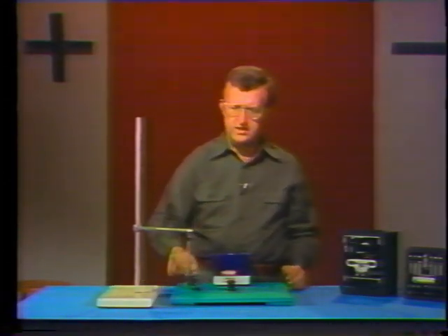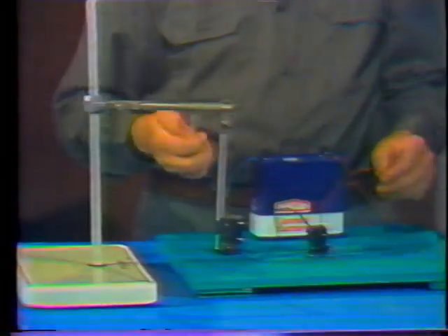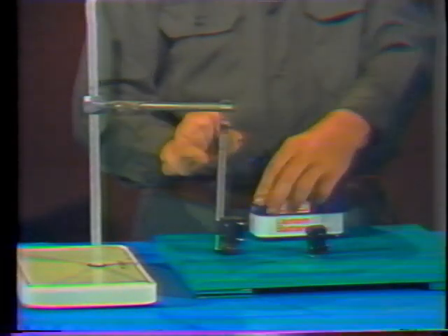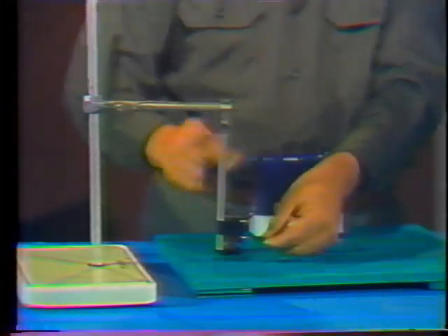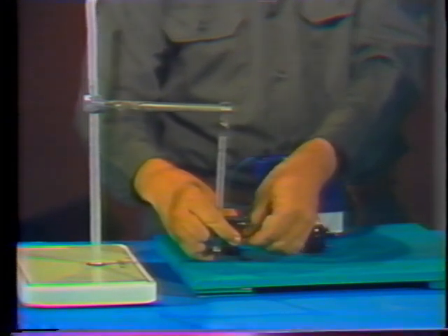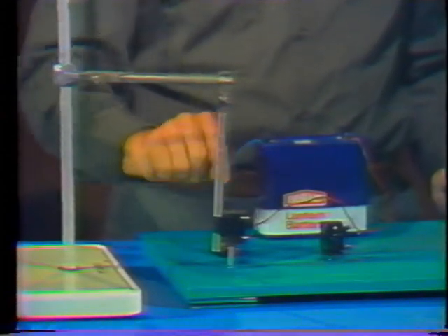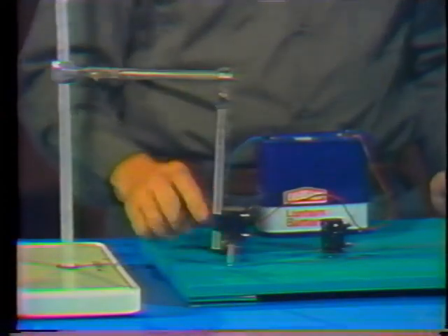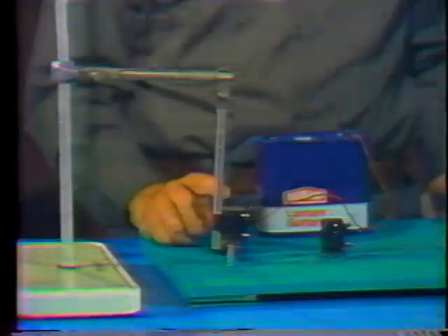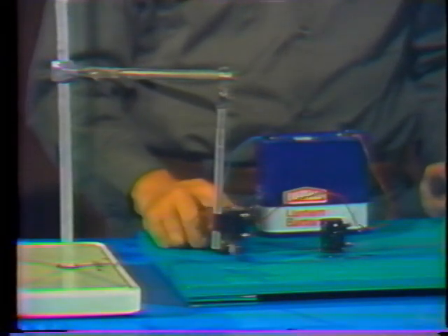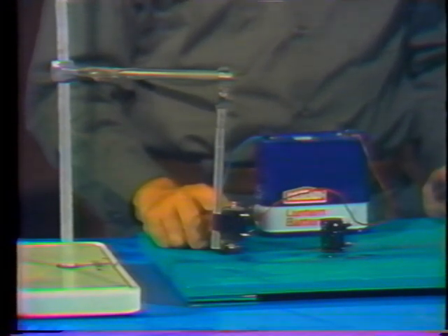I'm going to use a coil and an iron core to show you how a solenoid works. First, I'll make the coil a part of an electrical circuit. And having done that, of course that means we can send current through it. The iron core is positioned with one end on the table and the other end just inside the coil. And now, when I close the switch in the circuit, current flows through the coil, it becomes an electromagnet, and the core is pulled up into the coil. This action is what we call solenoid action.